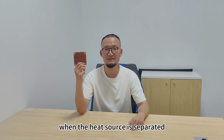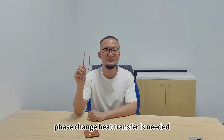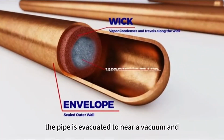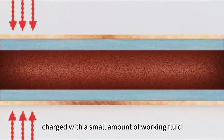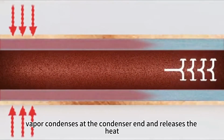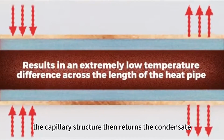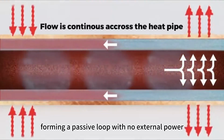When the heat source is separated from the cooling position and the space is tight, solid metal no longer suffices. Phase change heat transfer is needed. That is what a heat pipe does. The pipe is evacuated to near a vacuum and charged with a small amount of working fluid. At the evaporator end, the fluid boils and absorbs a large amount of latent heat. Vapor condenses at the condenser and releases the heat. The capillary structure then returns the condensate, forming a passive loop with no external power.